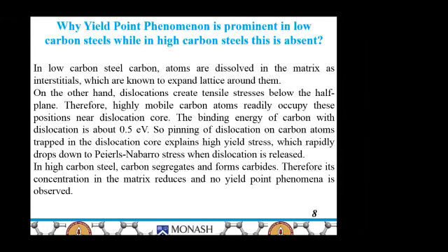Now, why is the yield point phenomenon prominent in low carbon steels, while in high carbon steels it is absent? This is a very important question. In low carbon steels, atoms are dissolved in the matrix as interstitials, which are known to expand the lattice around them.